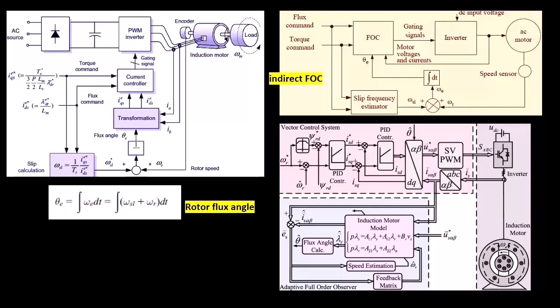Vector control, which utilizes sensors, remains the prevalent approach as it offers more precise and predictable motor behavior. By leveraging sensors, the system can acquire direct and real-time feedback, ensuring a consistent and dependable response, especially under varying load conditions and external disturbances. As the industry continues to evolve, there's ongoing research into refining sensorless techniques to meet the rigorous standards required for automotive applications. However, until there's a breakthrough that guarantees the same level of reliability and safety as sensor-based solutions, the latter will remain the standard choice for many manufacturers.